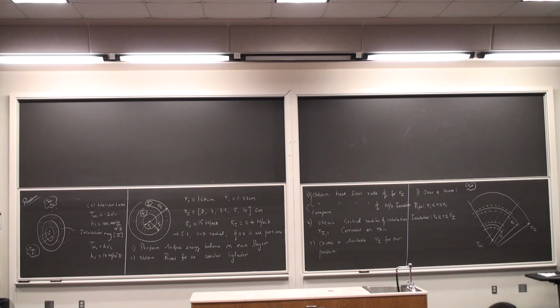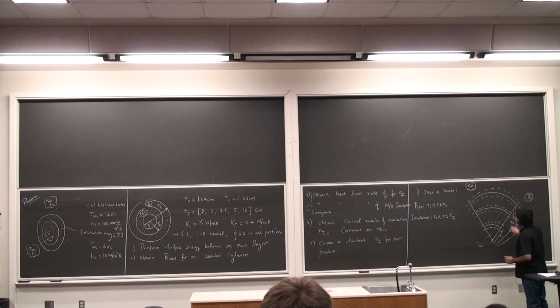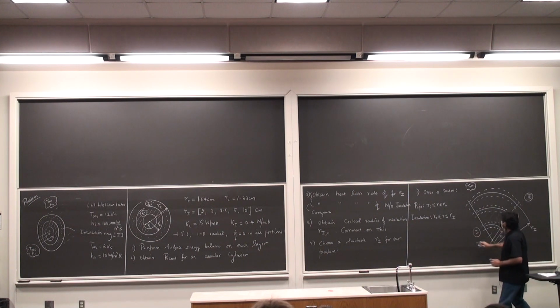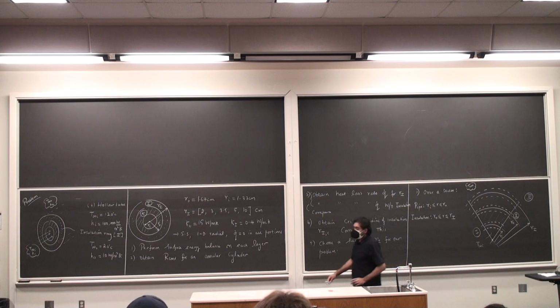Okay, and then my last one is going to be at the outermost radius of the insulation ring, and that's right there. Alright, so three control surfaces: 3, 2, and 1. No energy generation taking place within any of these, so we are good to go on that. Okay.